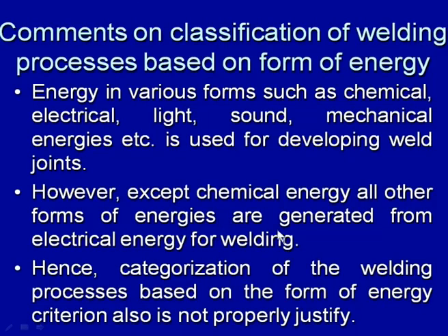So, in this way this classification becomes slightly confusing. Hence, the categorization of the welding processes based on the form of the energy criteria is not very properly justified. Except the chemical energy, all other forms of the energies use the electrical energy, and that is why this classification based on the form of energy is not very effective and properly justified.